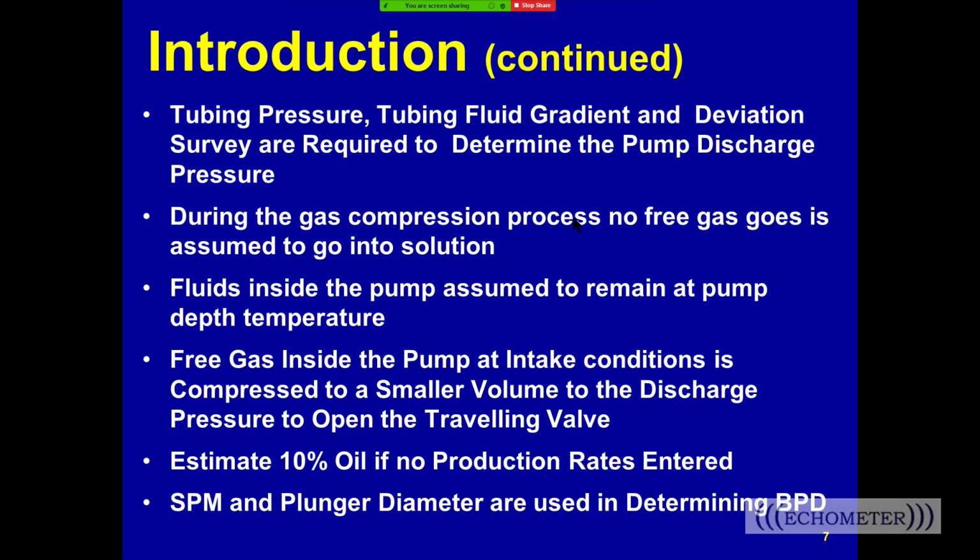One of the things that we assume during the gas compression is that the free gas that's in the pump with the liquid doesn't go into solution. Now, it can, if the oil and gas are in contact and it's shaken and the gas is compressed, then the gas can freely go into the oil based on the pressure. But we've got a problem in the sucker rod pump, is there's water, and often the oil and the gas are separate. So it's difficult to push the gas into the oil if the gas and the oil aren't in contact.